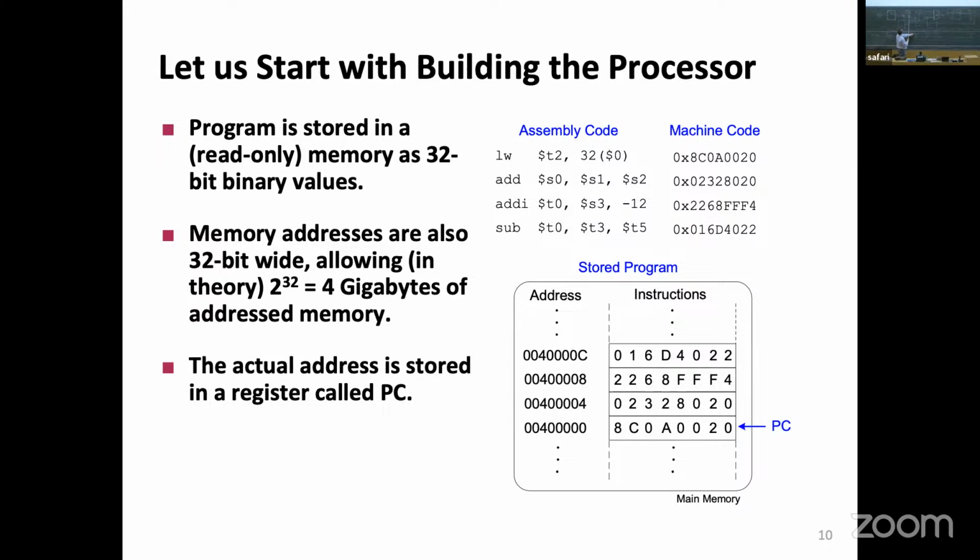Going forward, you realize that I'll be writing back to the register file, because load word will load something into the register file. I know that the ALU is always going to use the first register as one of the operands, but the second one doesn't come from the register file. Instead, it is part of the instruction, and while decoding it, I realized these 16 bits, I extend them so that it generates a full 32-bit value.